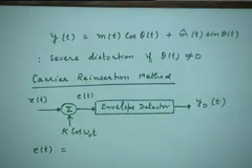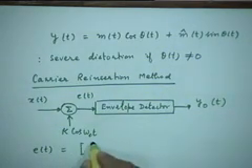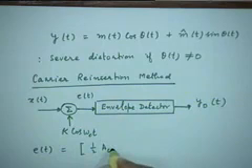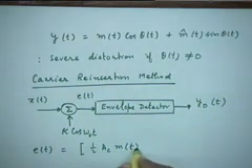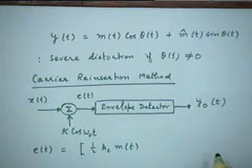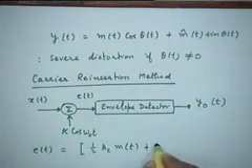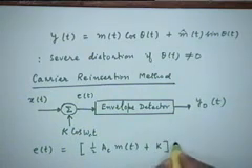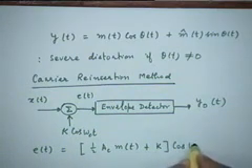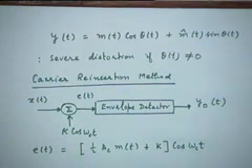So the cosine omega ct has two parts now. The in-phase part of the SSB signal was half Ac m(t), multiplying cosine omega ct, plus you have a constant amplitude carrier k here, and these two together now constitute the so-called in-phase part of the SSB signal.